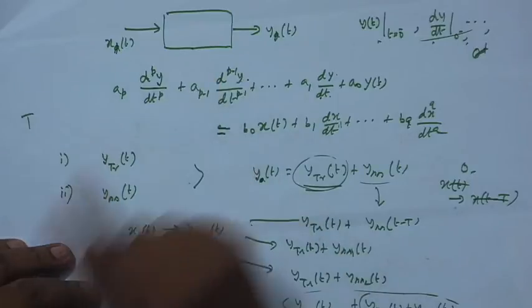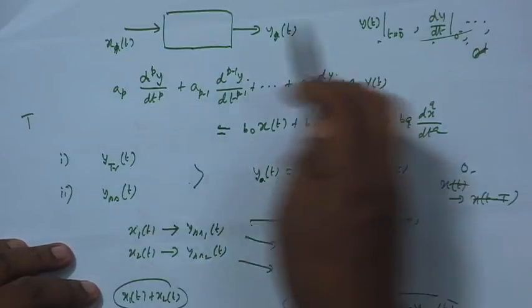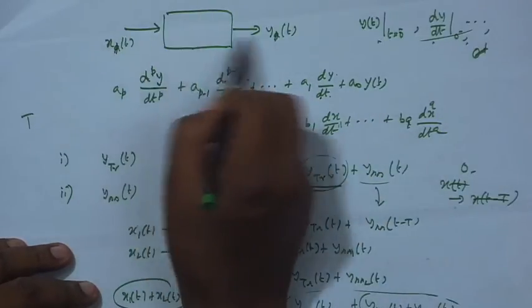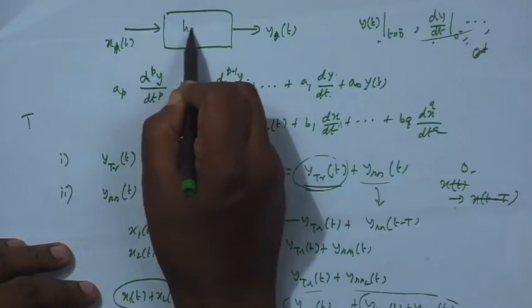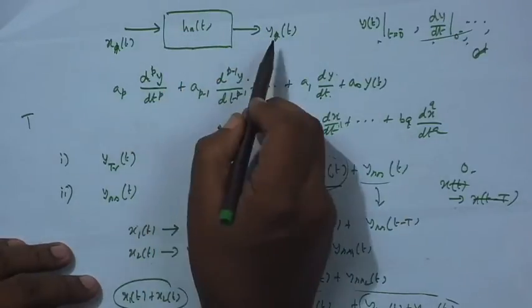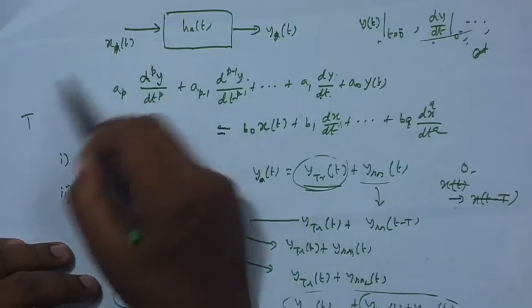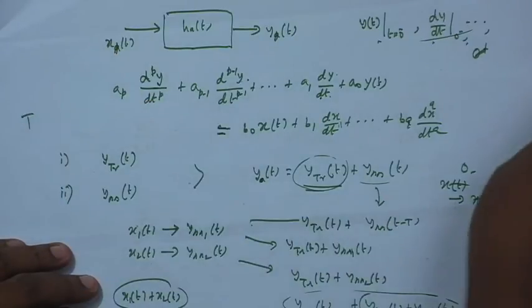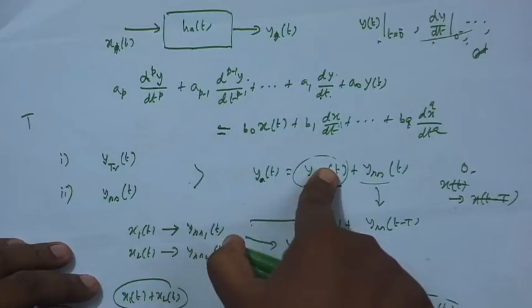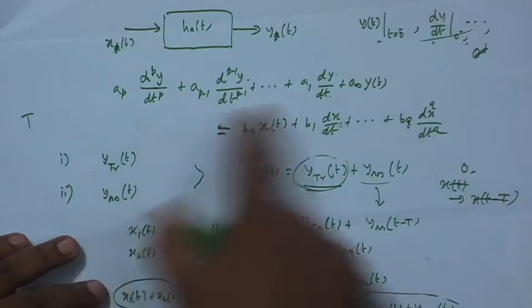So, it will be a linear and time invariant system, and therefore, if you give a delta at the input and record the output and call it the impulse response, then another way of obtaining the output will be convolution between these two. Okay. Under this case, the system is linear and time invariant because there is no transient solution, initial conditions are 0.